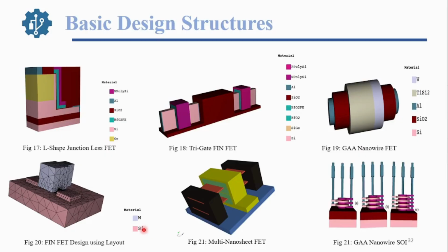These are some basic designs used and created in a TCAD tool. This one shows the L-shaped junctionless FET transistor. This one shows the tri-gate FinFET structure. This one is the gate all-around structure, like a dumbbell. And this one is the FinFET design, created using a layout.